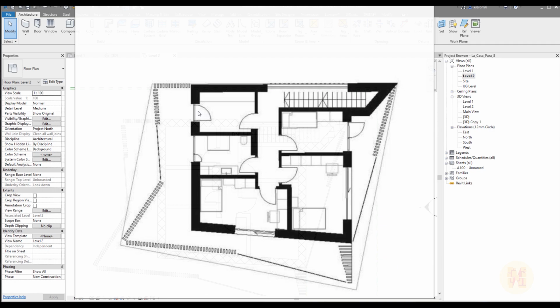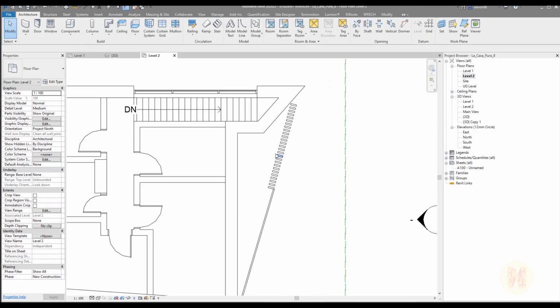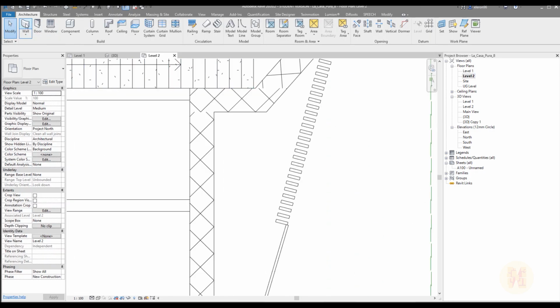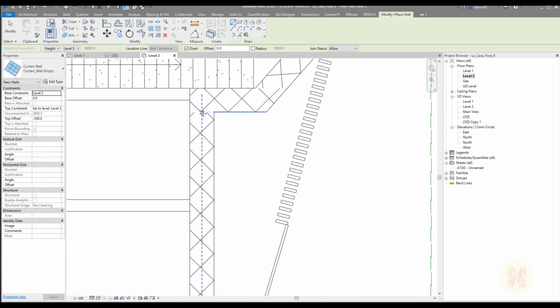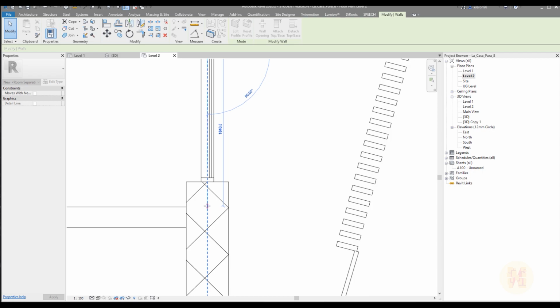Now it's time to create our curtain wall with the door. As you can see, the fixed one we have only once, but curtain walls with doors we have a lot, like 1, 2 and 3. This is some special one. I will create, for example, that one, and I will go to Revit. Here we are inside Revit, and you are able to use the same curtain wall. So I will use the same curtain wall. I will place it exactly as I want, somewhere here, and after that I will extend it manually.